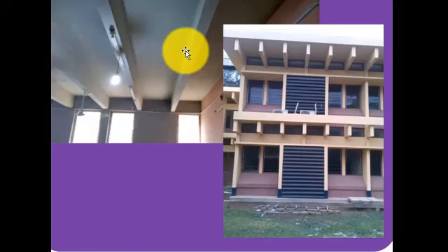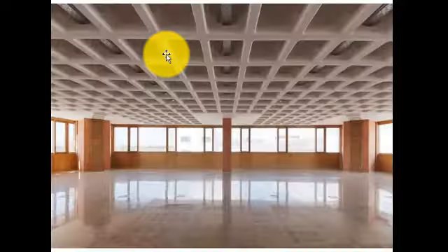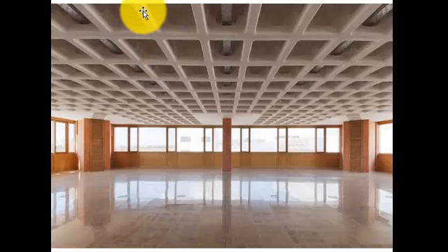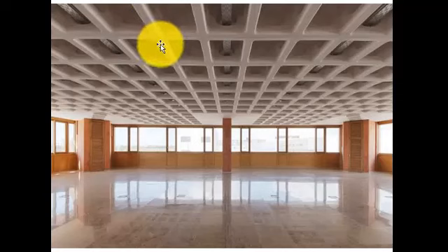So number 3 type of slab we are moving to is the rib slab. This is a rib slab. You see, some texts refer to this as waffle slab too. They call it waffle slab too, but they will now call it one-way waffle slab. Because let's go back to the waffle slab. Look at the rib of this waffle slab. How many dimensions is it in? It is in 2-way. There's one going this way and there's another going this way.